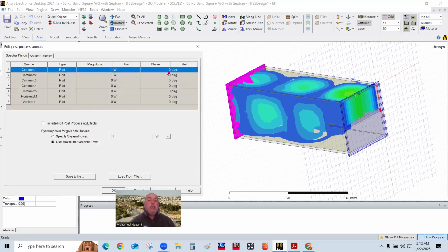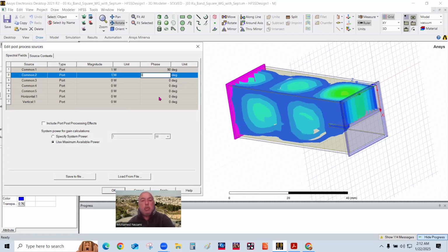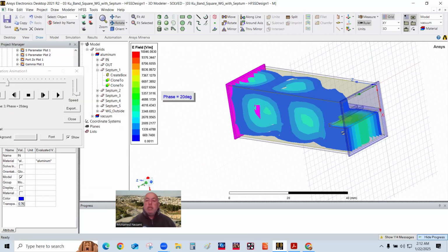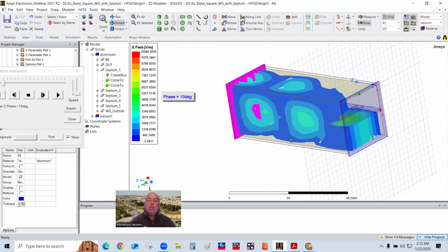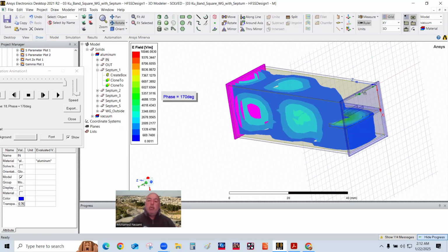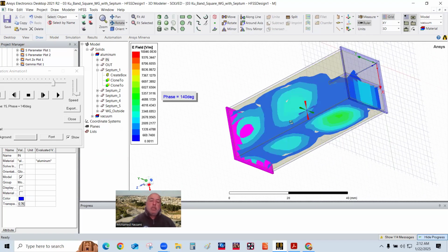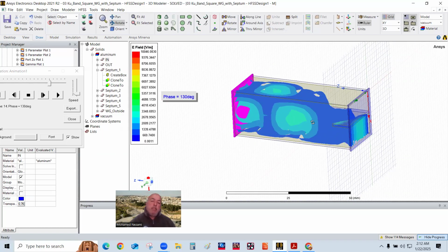Let's say that the E field was, let me do this one is 90 degrees and this one is 0 degrees. So I'm just swapping the vertical and horizontal. And you can see it's going to go to this port. Okay, see that? What happened? Depending on whether it's right-handed or left-handed, you're going to end up in one of these waveguides and not the other one. And this is really the principle of the dual polarization LNB feed mechanism.